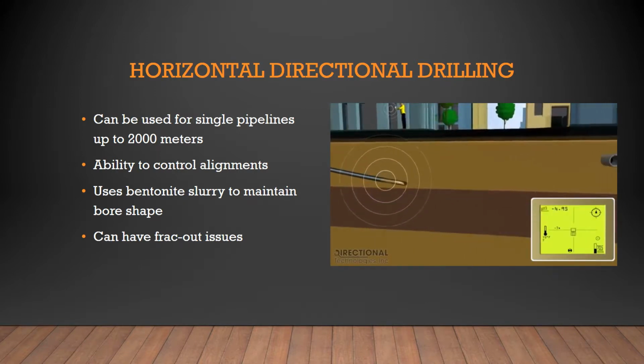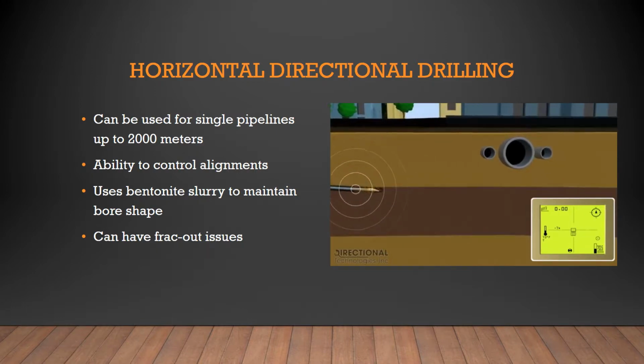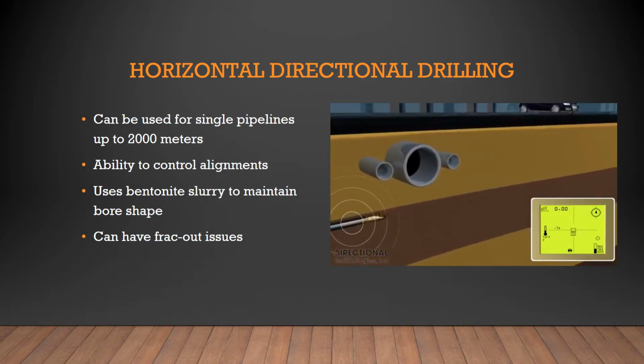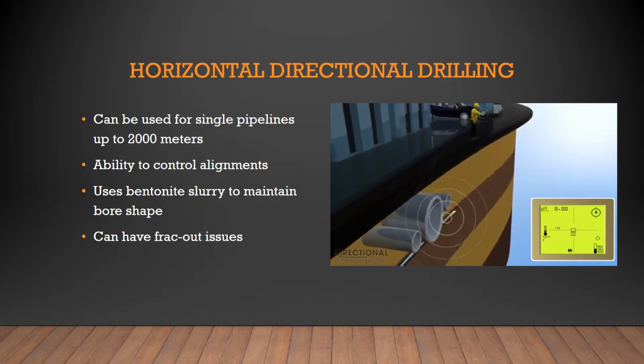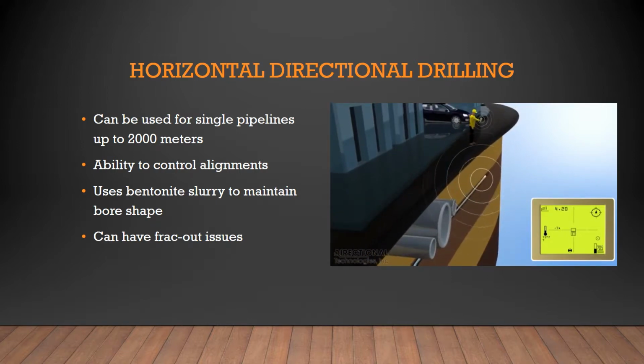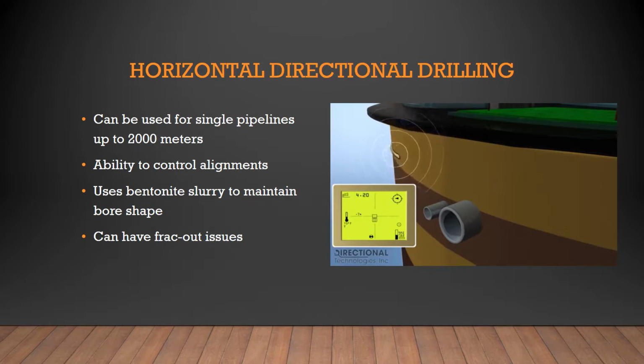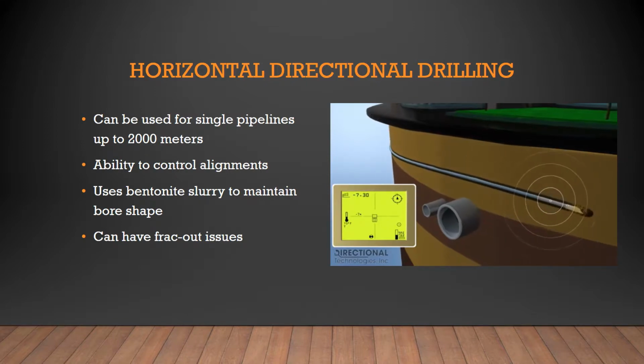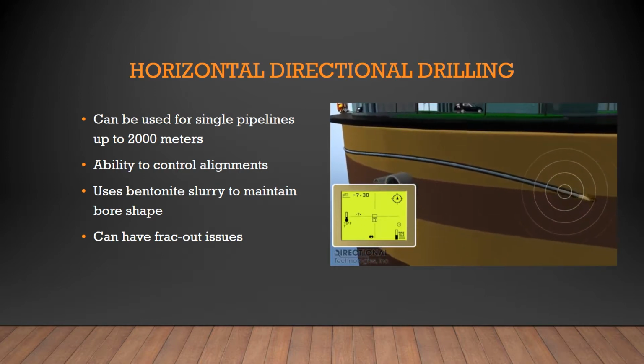The directional drill bit is tracked by a sonde, our radio detection device, housed within its extended connection to the directional drill pipe. The depth and pitch is sent to the surface and received by the walkover locating device. The locator then gathers and interprets the information and gives directions to the directional drill operator on which way to steer the drill bit.